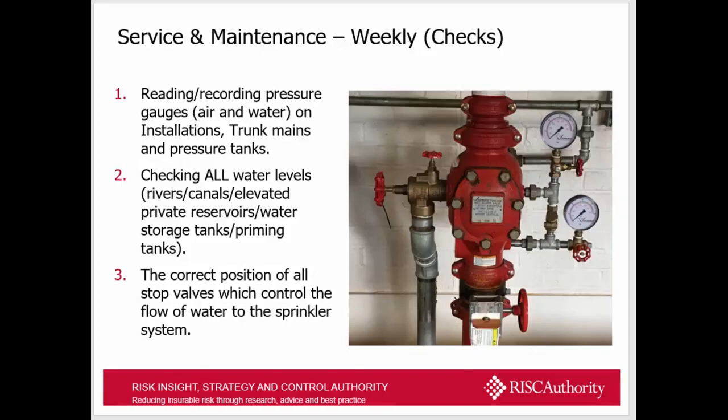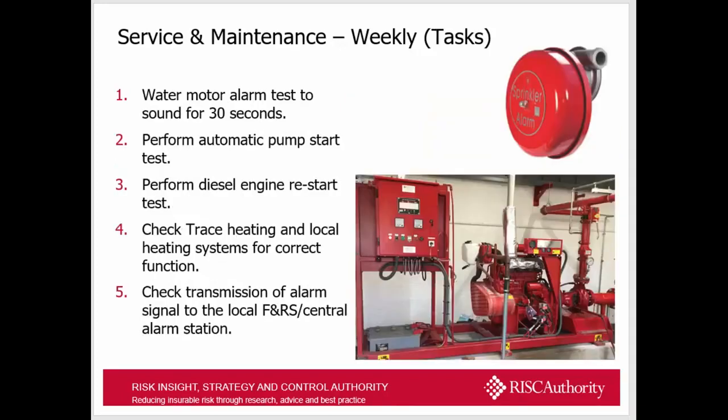So that's a requirement. Check all water levels. If you've got water storage tanks, or if you're using rivers, canals, private reservoirs, that there is water available at all times. And as mentioned there, the correct position of stop valves, which control any flow of water to the sprinkler system, they should be checked on a weekly basis. And this isn't a maintenance thing, it's just a visual check to make sure things are done.